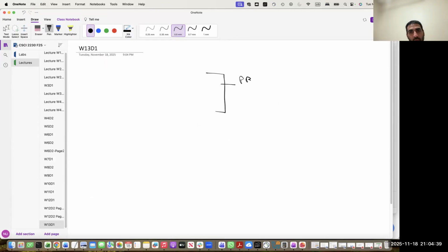So here is your port B, pin 5, and we want to set it as output, right? Now, you are saying, why are we not using the DDRB register? We can.